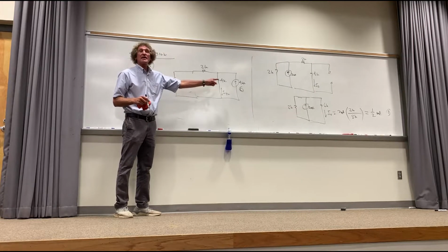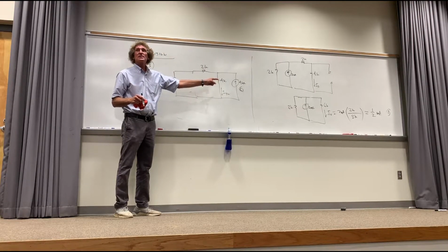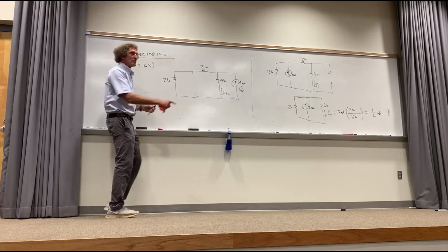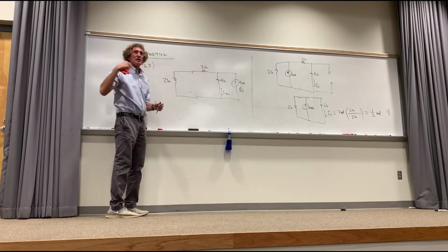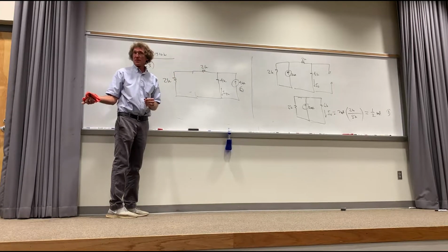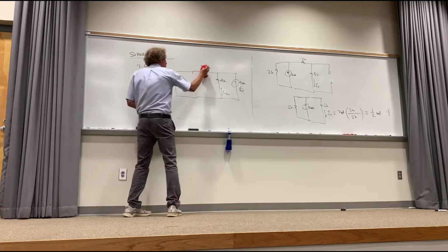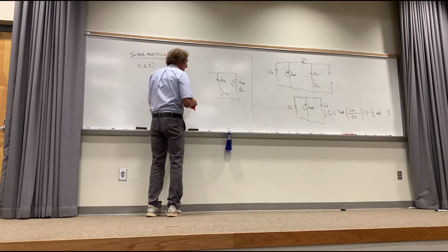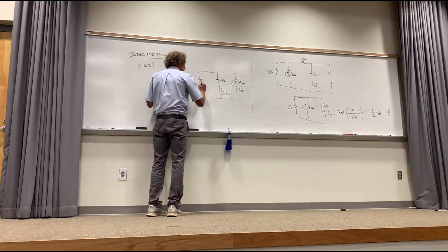We lit up that second source now, right? We turned off the first source. Everybody see this, please just bear with me. I'm trying to make a point here. Now, what do you see about these two resistors? They are in parallel, and the net is 4K. So couldn't I just do this and make this 4K? Right?